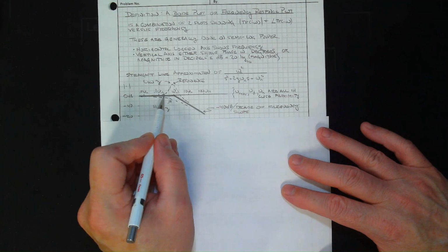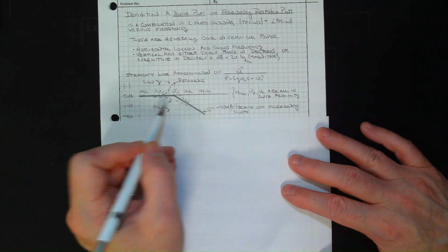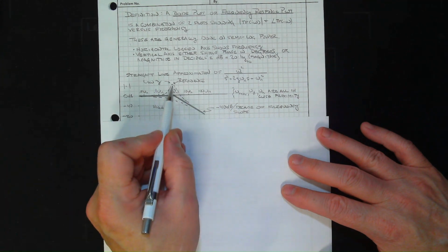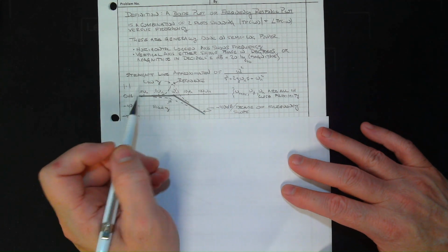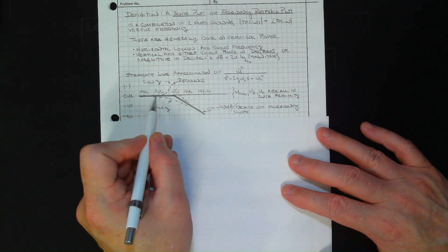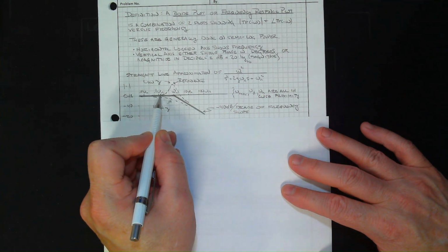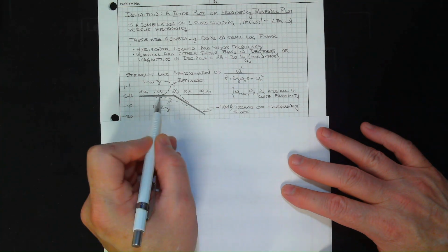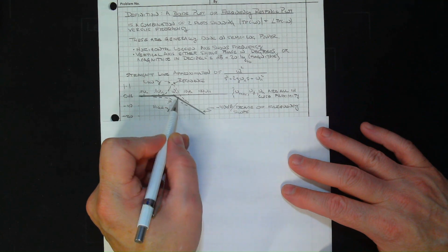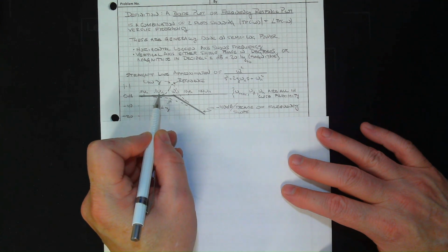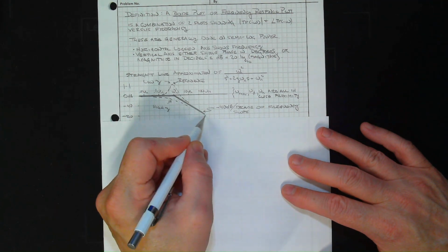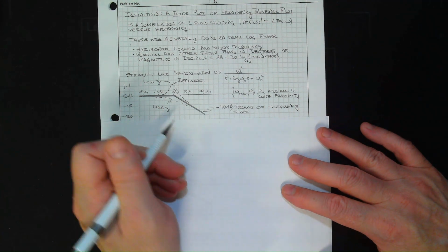Around the resonance, you're going to get some growth, and depending on the level of the damping, it will determine how high that is. Okay, if you have really high damping, you'll have your growth, you'll have a little blip somewhere up here, say, but then relative to this straight line approximation, it'll come down and it'll be a little bit underneath this, and it'll drop. It'll eventually match up with this minus 40 dB per decade.